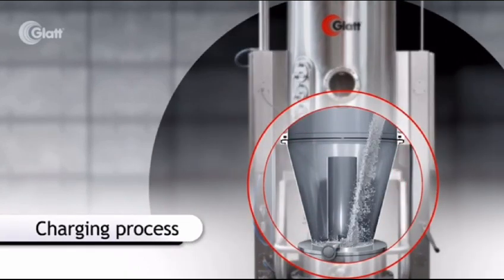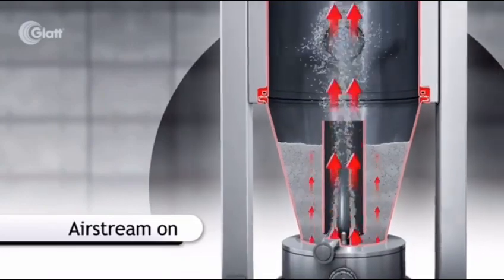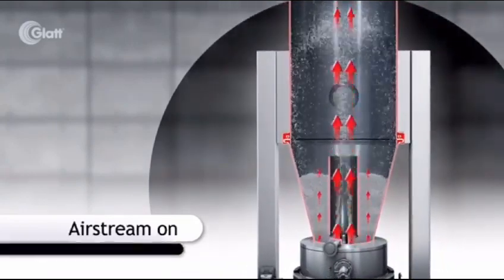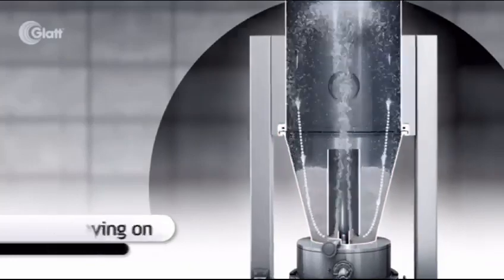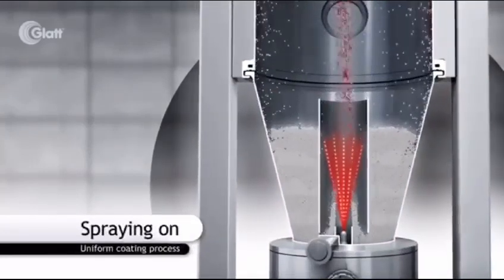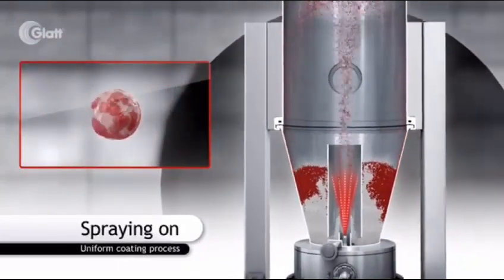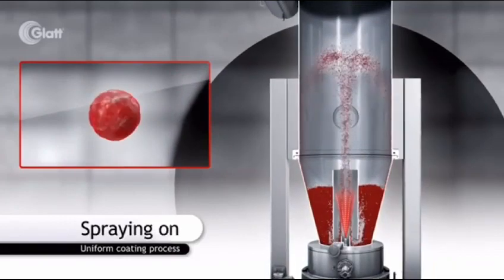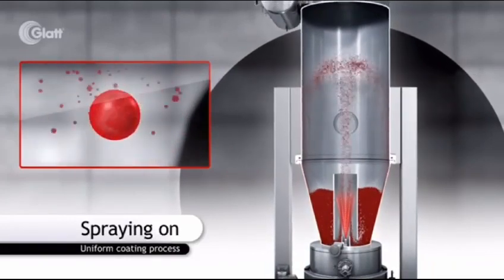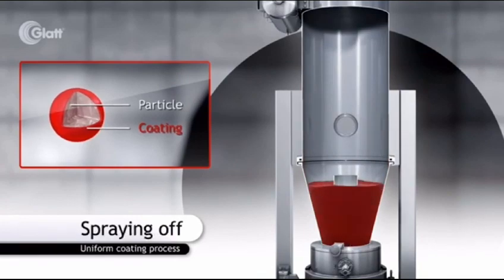Number one step we have is the charging process, in which the tablets are filled in the columnar chamber. Now the air stream is on, which will blow hot air onto the tablets. Now the spray is on, through which the material is sprayed onto the tablets. See, just like this, the material will coat each tablet. We can see here a film is coated around each tablet.